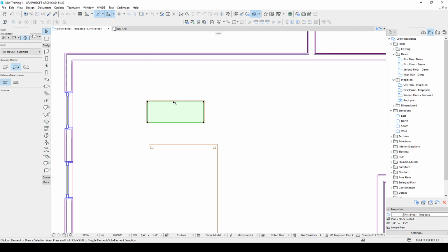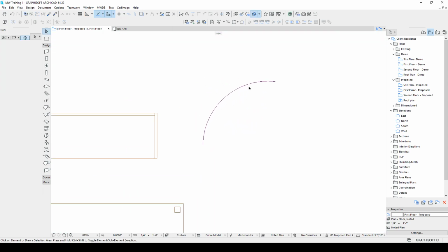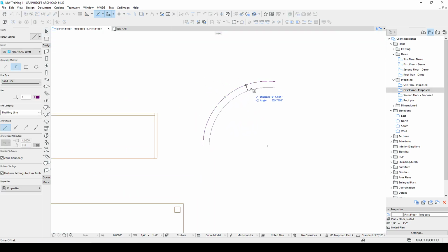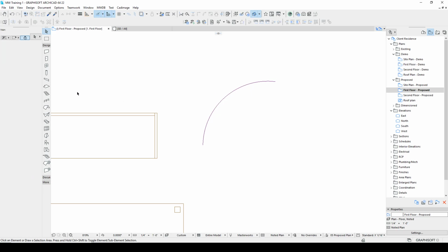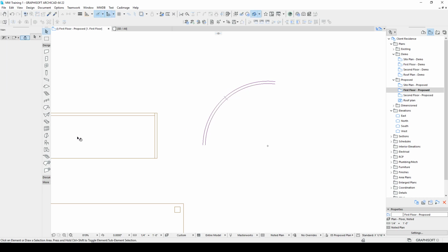It could be a curved cabinet. So if I drew a circle, did line offset, so I did, let me slow down on that. L for line, O spaced, marquee that, or magic wand it, 0.75. And if I go pick up the properties of this back, that's good.